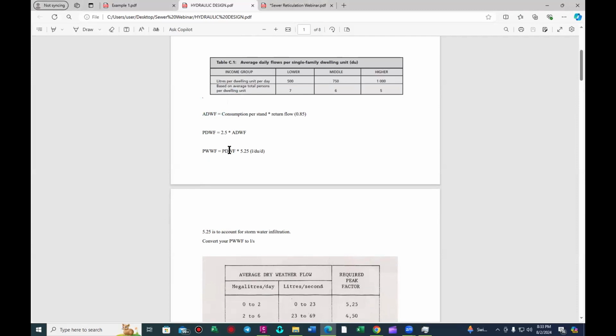You have to understand that people are not going to all go to take a shower at the same time. People are not going to do dishes at the same time. But we can, by general approximation, tell when we're going to have peak factors. And by culture, usually we're going to have peak factors in the morning and the evening. Usually in the morning because people are preparing to go to schools, people are preparing to go to work. So everybody's taking a shower, people are cooking. So we're bound to have peak factors.